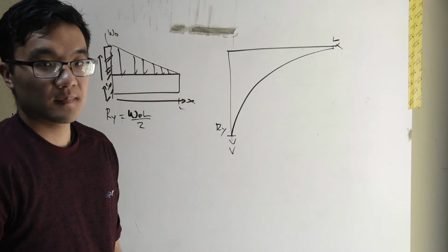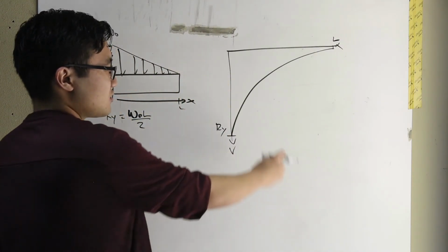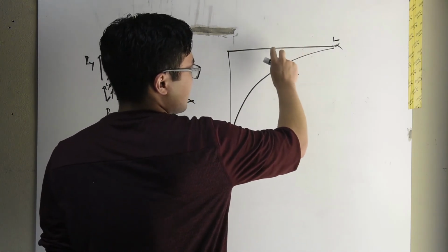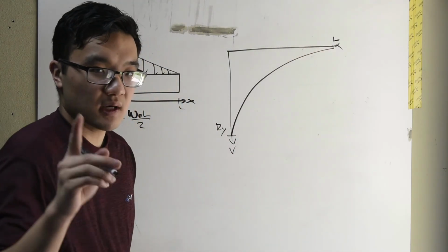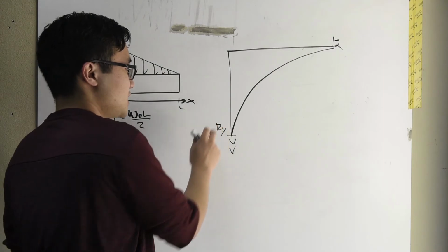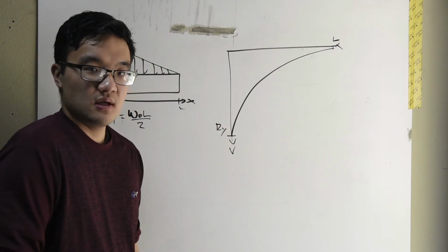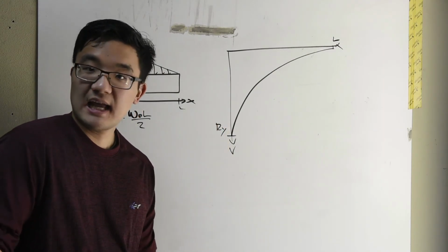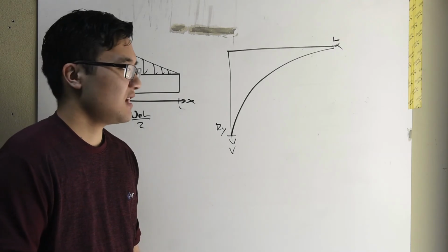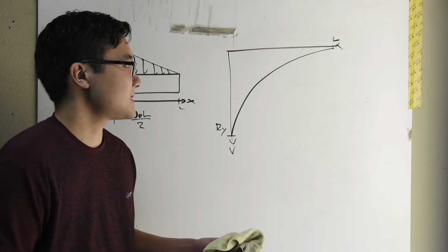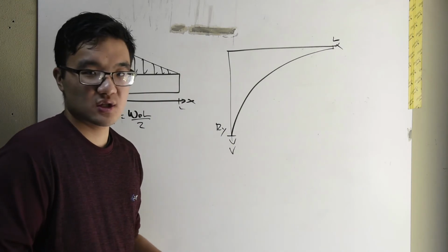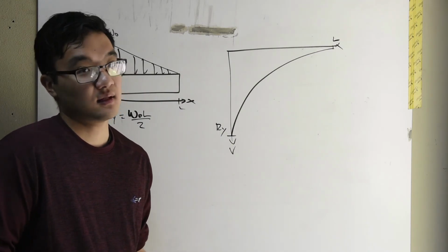Remember, basic curve. What this is saying is the internal shear experienced further out on the wing is much, much less than the shear experienced at the root. So therefore, we can save material weight, we can save material amount, all of that stuff, at the edge of the wing because that's not taking the load.